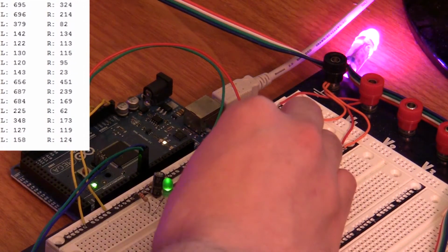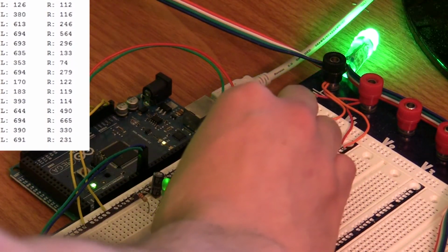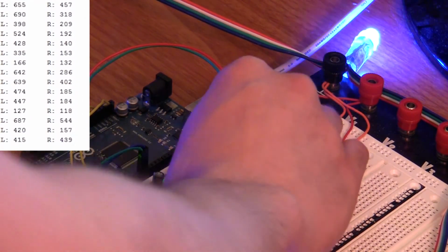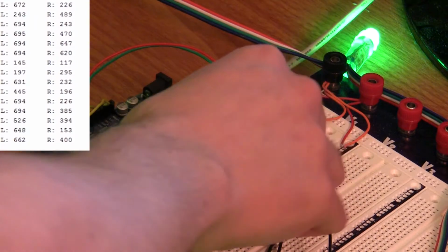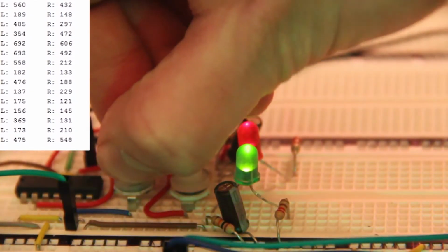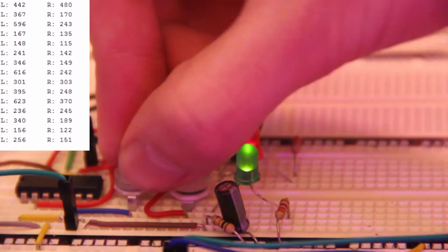And you can see that if you look at the serial monitor, it changes the maximum and minimum possible values for the serial input. So before we guessed that it would be from 0 to 400, but we can really see that it's going up to 600. So you might want to consider changing that. But depending on how you tune the potentiometer, you're going to get different values.